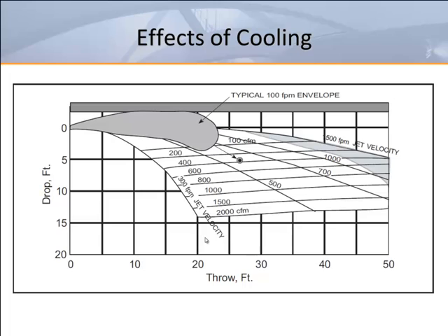To provide consistency, most catalog throw performance data is shown with isothermal air, no heating, no cooling. When mapping, to assist with knowing the throw and drop from a cooling jet, there are 6 charts on the website and in the catalog engineering section, similar to the one shown here, to estimate performance.